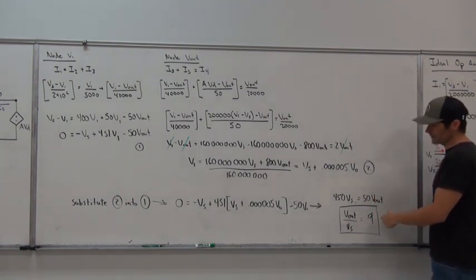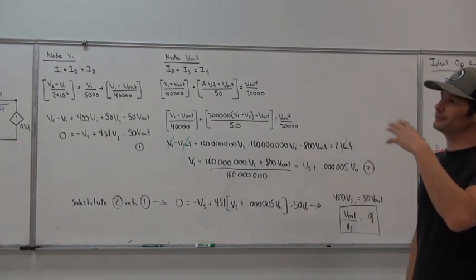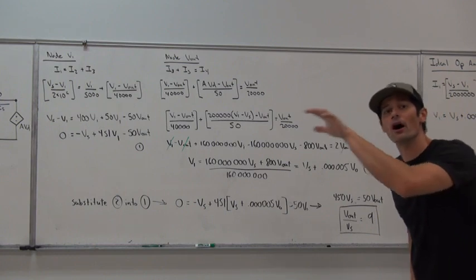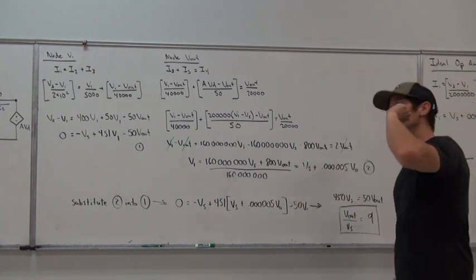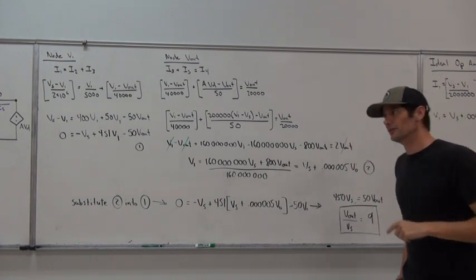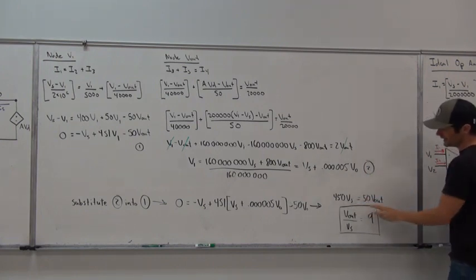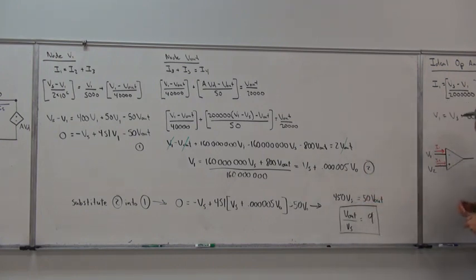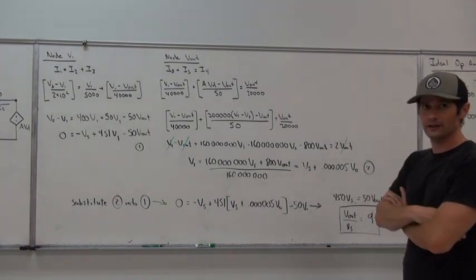And not only is it a factor of 9, it also shows that by connecting Vs to the positive terminal of the operational amplifier, we do not perform an inversion in terms of polarity. We keep the same polarity as the input, so Vout over Vs is equal to 9. All right, it's pretty messy, right?